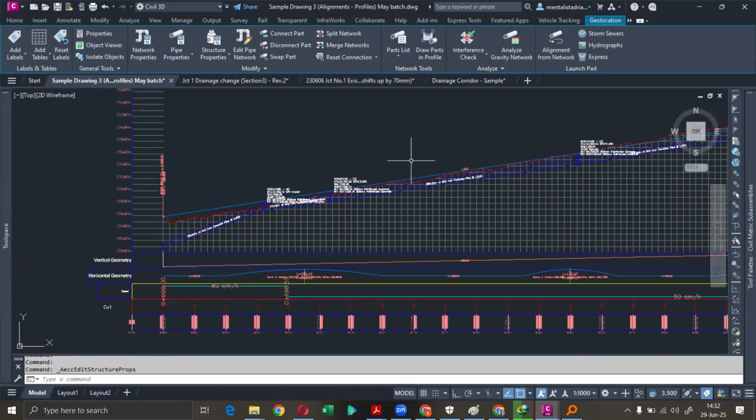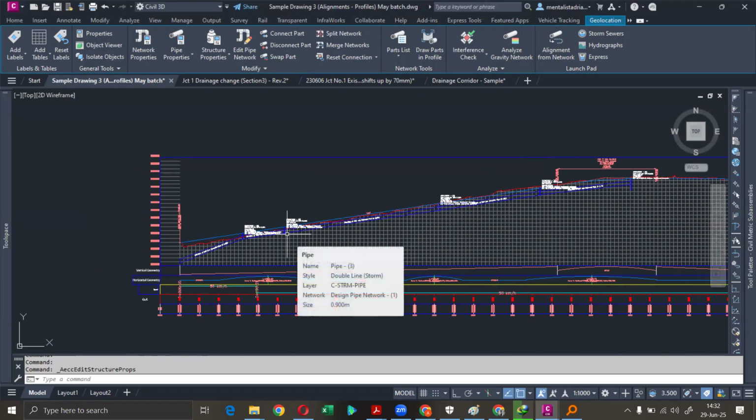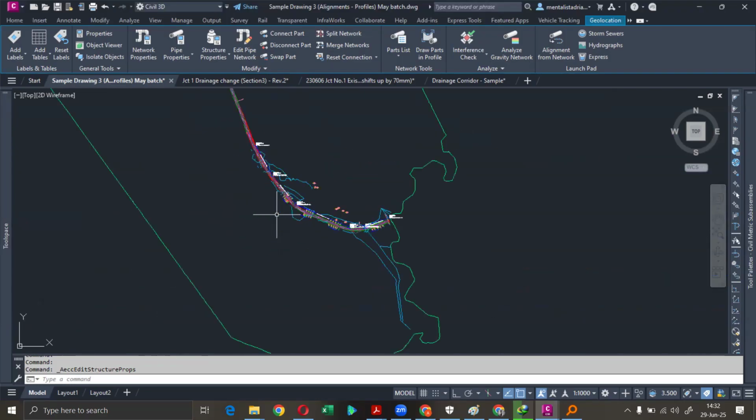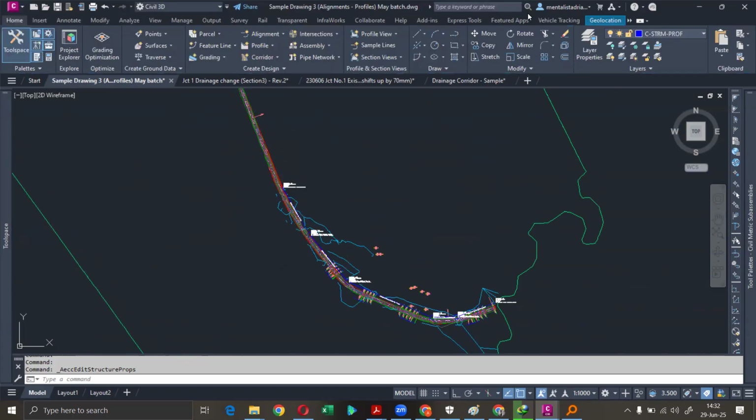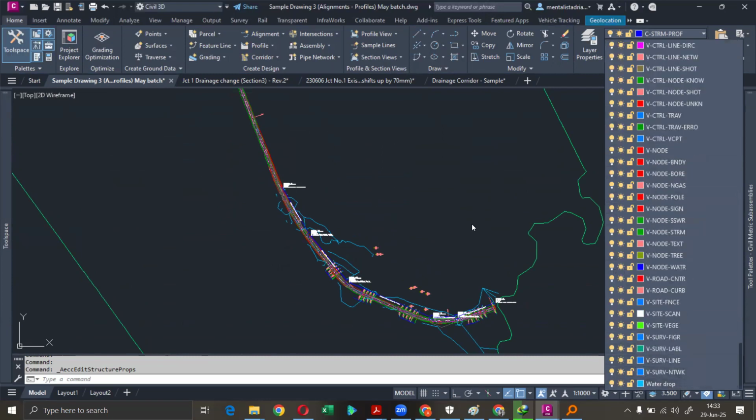But some things that will make you frustrated are drainage works, because with drainage there's very small room for error. If you make any mistake, I think it will just not work. If your slopes are not right, they will not flow how they're supposed to. So either way, you need to have it right. Let's say that okay, we have done all this. I don't know if there's any more questions before moving on to the cross sections.